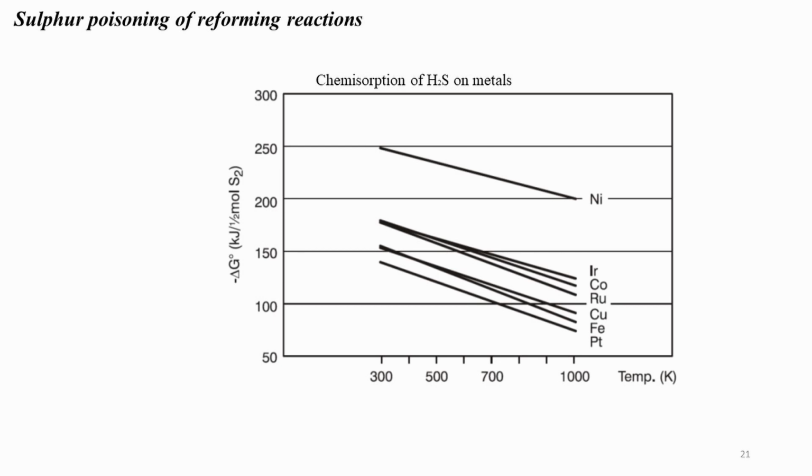Group 8 elements are susceptible to sulfur poisoning, and sulfur must be removed from the feed stream. Natural gas may be cleaned over active carbon, but normally all hydrocarbon feedstocks are treated by hydrodesulfurization over cobalt molybdenum or nickel molybdenum catalyst, followed by sulfur adsorption on a zinc oxide adsorption mass.